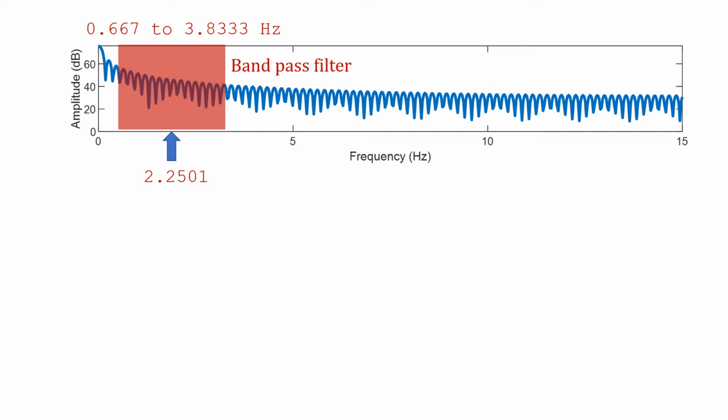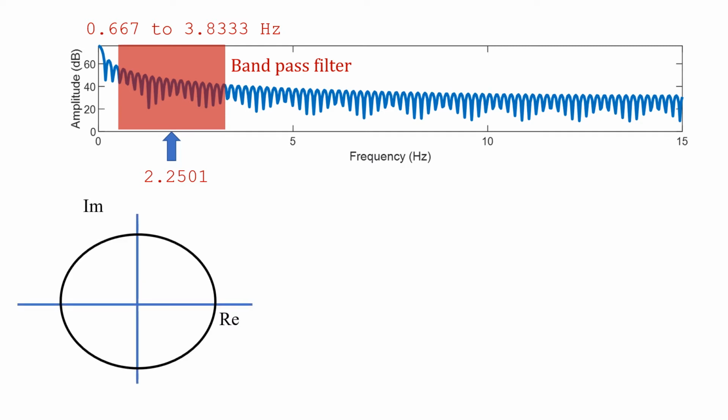Now, if I would like to design this filter by placing poles and zeros, I can do that by placing a pole right there, and I will name it P1, and I will be evaluating the distance between that pole and values in the unit circle. That's the angle of the pole at various specific frequencies. So e to the j omega will be traveling along that circle.